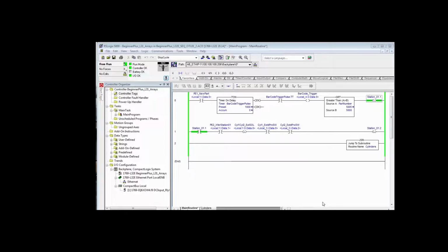Now the part is traveling on the feed conveyor waiting for photo I2. I'll turn that on, and after some delay we see the extend proxies, and I'm going to turn photo I1 back off because I'm going to assume that when cylinder 2 is all the way forward, that photo I2 is not seeing the rod on the cylinder. We'll just assume that you mounted it physically so it looks underneath of the rod. So there we are. We now have the part pushed into the station.